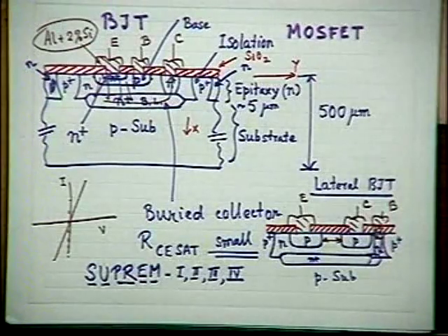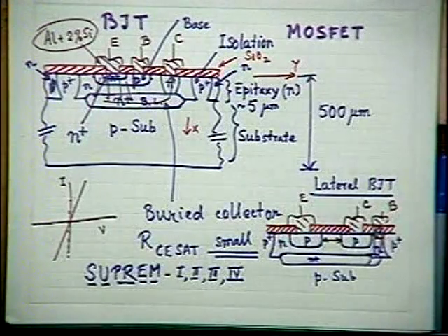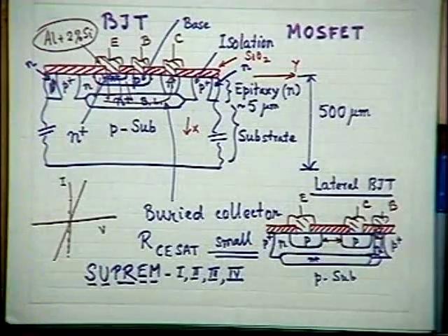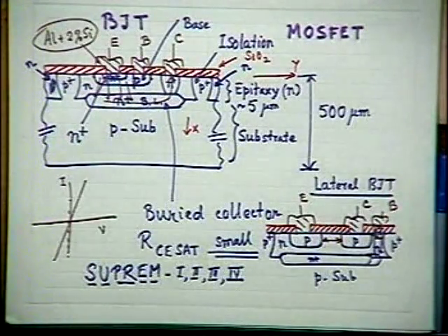So you can control your temperature, time, implantation dose, energy, etc., and get a profile. Using that profile, I then have to analyze the device, the bipolar transistor. I have two inputs: one is the doping profile, and second is the structure plus the dimensions of the mask.